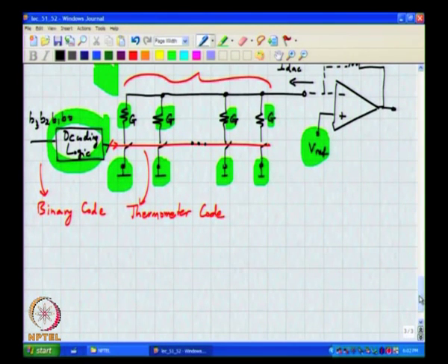So, now let us try and figure out what the ideal output voltage will be, the ideal current will be for a code M. For a code M, the current will be M times G times Vref, but unfortunately every G has got some random error, and if M conductances are on, it means that there will be M random errors.